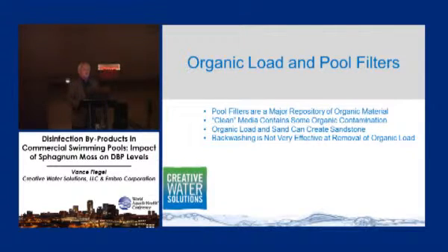We've done experiments in our laboratory where we've taken clean, out-of-the-bag sand, and it already has some organic contamination present as it comes out of the bag. As we know, if we see really dirty sand filters, the combination of the organic load and the sand can create a kind of sandstone within the filter, which makes the filters very ineffective. As the particles get bigger and bigger, the filtration efficiency goes down and down.